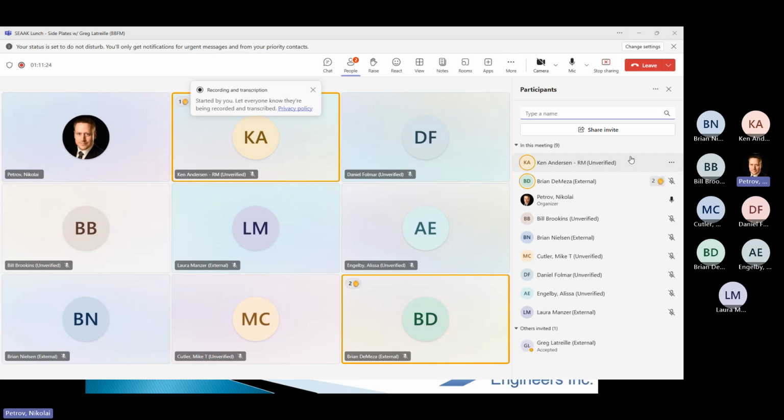I looked at other things. How much movement did we get? Is there something here that makes me feel that, yeah, we do want to open a wall and look into it? Is there a lot of cracking around windows? Is there just a lot more movement than I would have expected? But certainly, there are a lot of moment frame buildings that haven't had that sort of deep look into how the connections did. Is there any cracking?